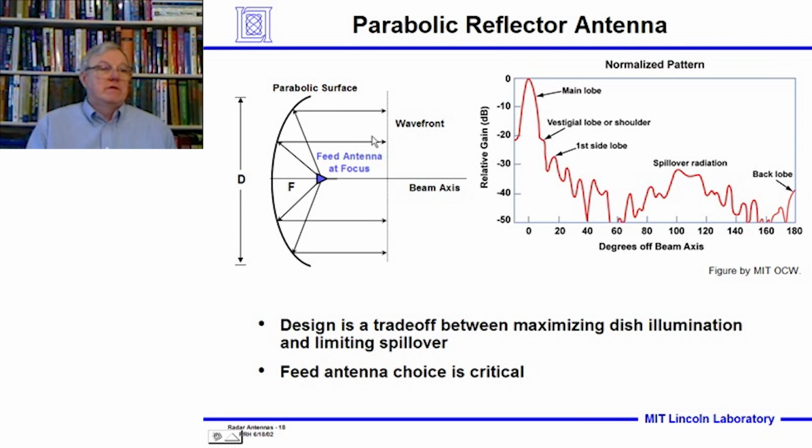And if I have the energy focused too narrow, then the effective diameter of my antenna won't be that big. I would like to see uniform illumination of the whole parabola and then none afterwards. That assumes things you just can't do in a feed very well. You can taper the illumination of the feed. That can help out. But anyway, for a realistic antenna, there are all these different areas, and I'm just going to go over them for a minute.